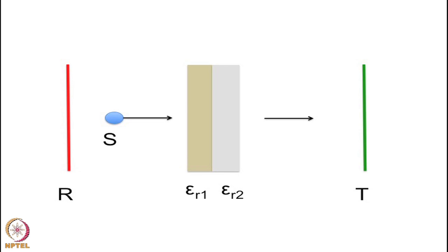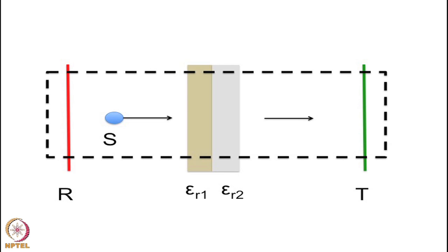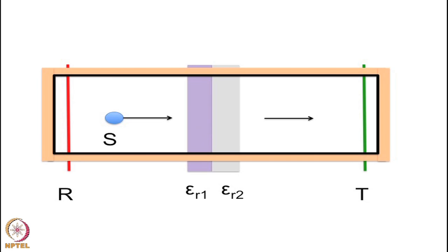So what you're basically modeling is Maxwell's equations, and you have the basic source information. You have the boundary. Do you have any specific boundary conditions you're forcing? Yes. I am forcing a boundary condition which I can show here, our simulation boundary. So we are truncating our physical domain. And what kind of boundary condition are you forcing here? So here I am putting PML on all sides.